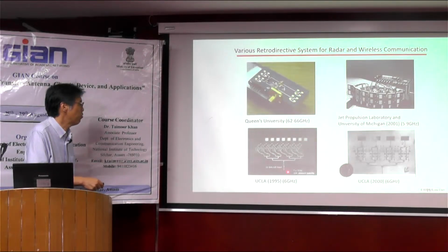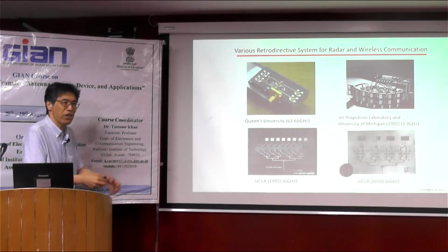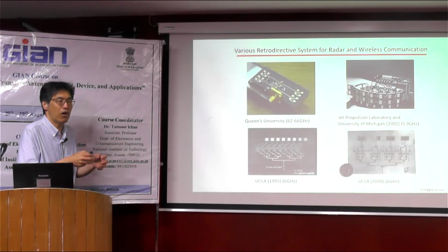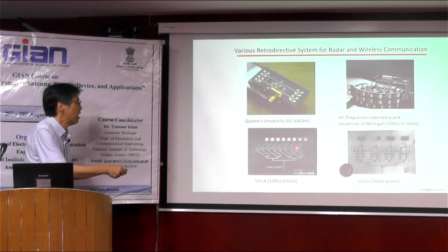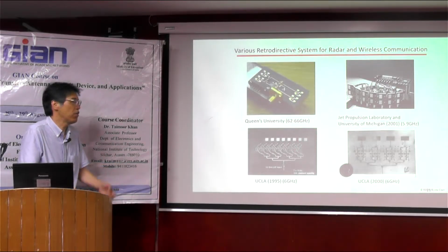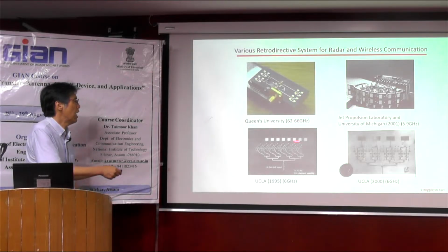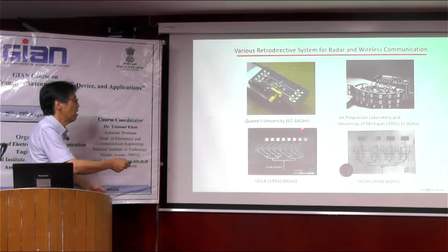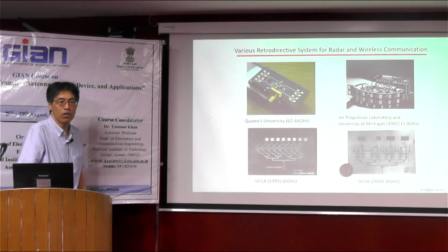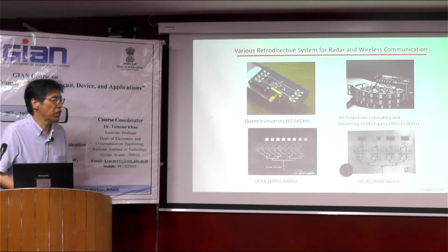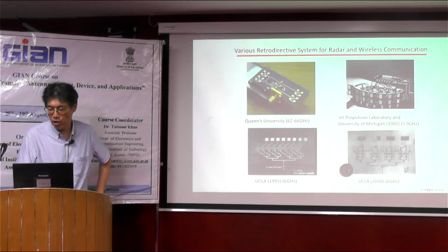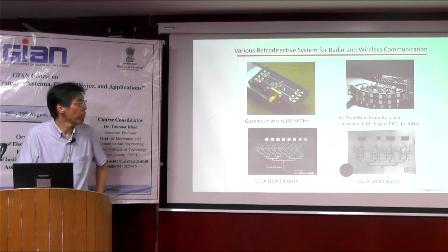And here we put a local signal with a double frequency, and we divide this local signal to each mixer. And we mix the local signal and the incoming signal. And from this line, we create the phase conjugation, and at last, this radio wave chases the target. So these are very interesting, well-developed retrodirective systems.